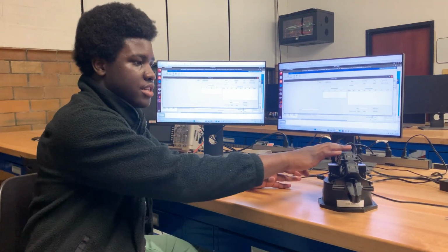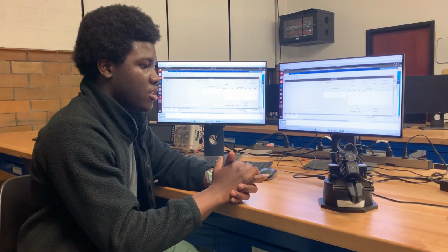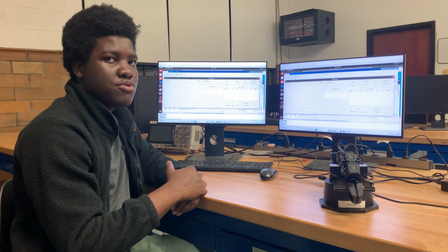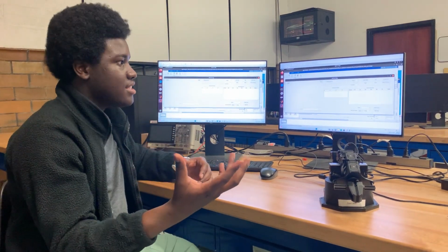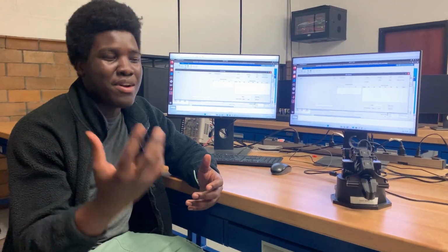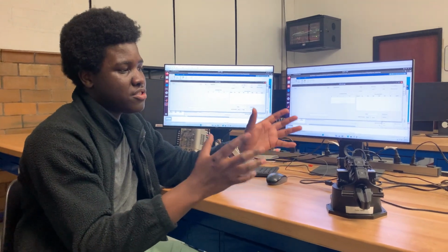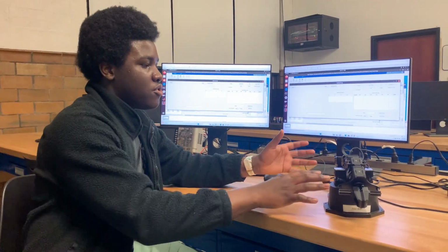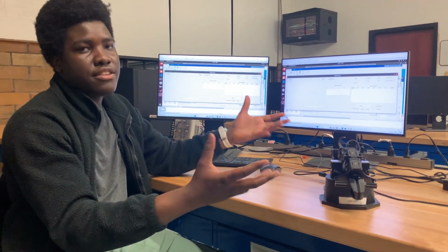We modeled each of these parts in the life-size model using SolidWorks. We're able to move that into MATLAB, and then with its GUI, we're able to display that, and then using inverse kinematics and Denavit-Hartenberg parameters, we're able to create a very robust application, a very robust software that maps all the different coordinate systems of all the parts and makes this an effective software.